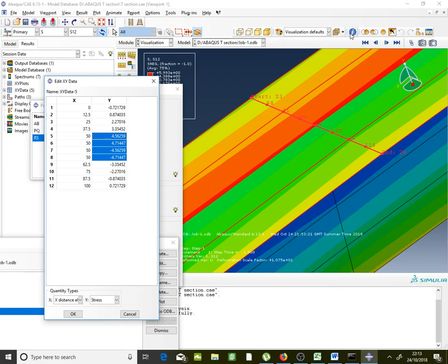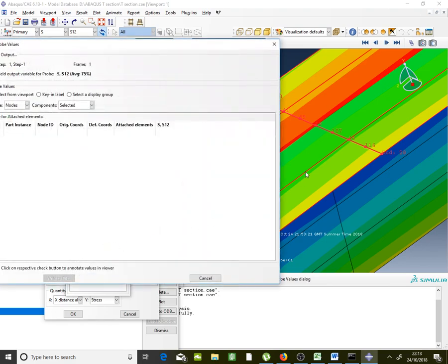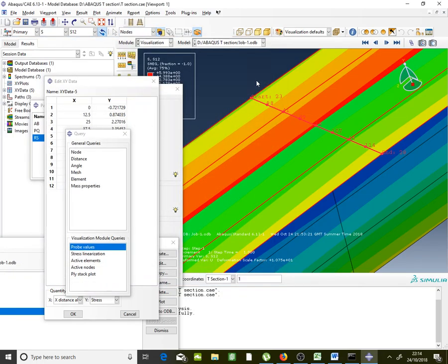If you click on I here, click on the node, prop value, if you drag it a little bit here, you'll find minus 9.36, minus 9.36. All these values are for the web, and the rest of these values, 4.56, 4.71, minus 4.71, minus 4.5, are values from the flange. Now close it. Now you know where it comes from.